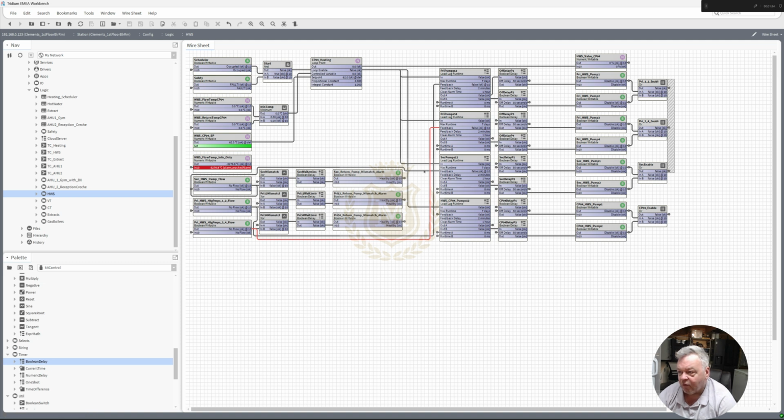As for the secondary pump, we've got the flow there, secondary pump's flow, but there is another one, this one here, CPO4, our feedback, because we don't have the flow as a point coming in. All I've done is, the output that we are sending out to the pumps, I've just put an OR gate in there and attached that to the flow.